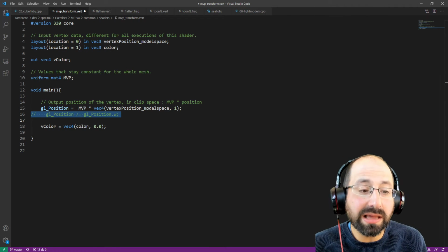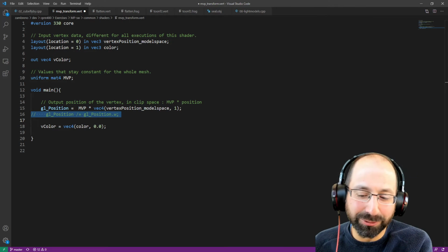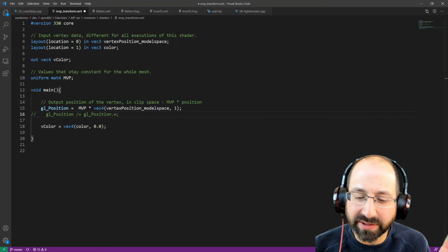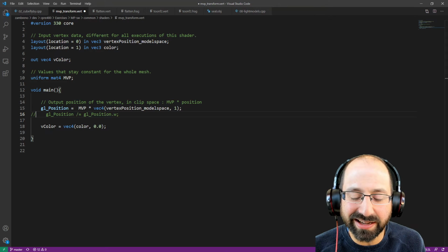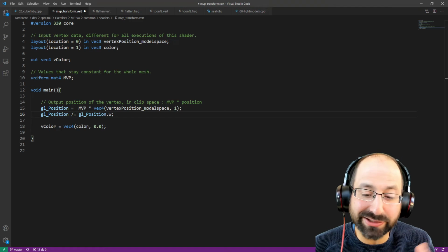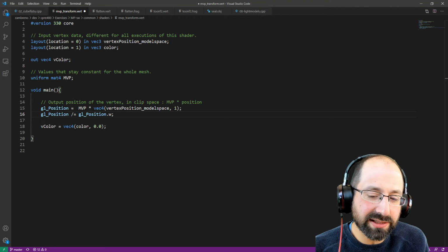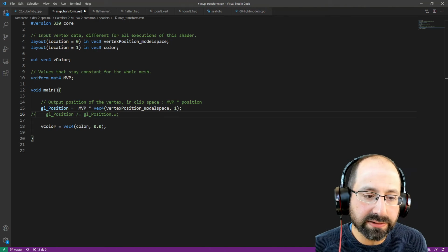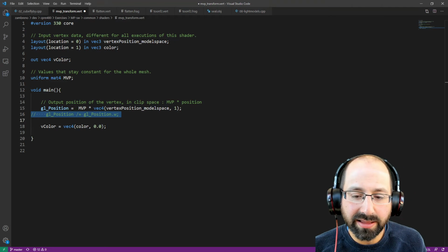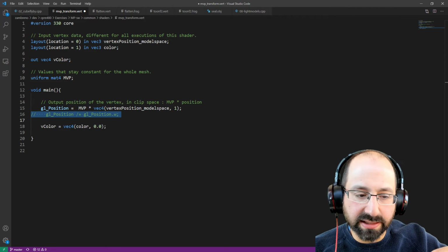But when you get to that point where you have a cube working on your monitor, working in hardware, and you'd really like to get rid of that warped kind of fisheye view of what's happening in it, that would work. It's just new. It's not necessary in real hardware. So why is it not necessary for ours? Well, we either have to add a fixed function piece of hardware that always does that division for us, or in our compiler infrastructure or driver infrastructure, we have to add that as kind of an addendum to what our shader compiler otherwise is emitting.